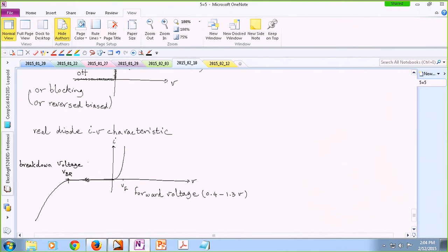All right, so you should make sure that while you are using this diode in your real converter, you would not get close to this number. Again, this number also appears on the data sheet. So if somebody tells you I have a 200 volt diode, that 200 volt is referring to this breakdown voltage. And in a practical case, you shouldn't go beyond 150, or have a little bit of a margin for yourself, a safety margin.